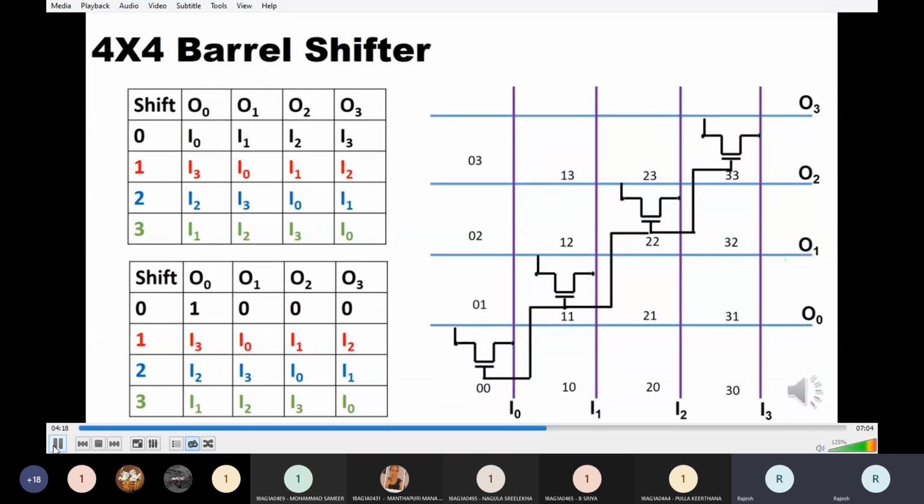So the control signal or gate signal of each transistor must be shorted. Whenever we make gate input 0,0 high, it makes all the gate terminals of the transistors, that is 1,1, 2,2 and 3,3 high, and all the transistors are on at the same time, and they connect input 0 to output 0, input 1 to output 1, and so on.